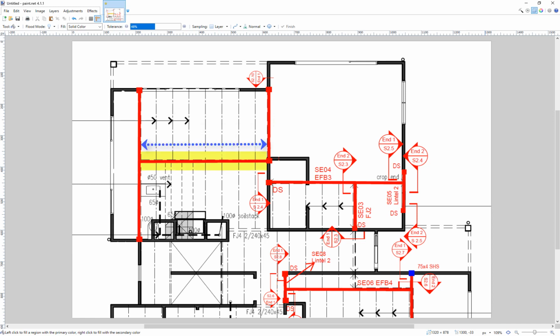This beam is 4.8 meters long and is supporting a floor load. Because the floor joists are perpendicular to the beam, the span being supported is the distance between the two load-bearing walls, which is 5.2 meters. End 1 is supported on a 2.6 meter high post, which lands on an internal pad foundation. End 2 is landing as a point load on a beam supporting the second story, element SEO2.